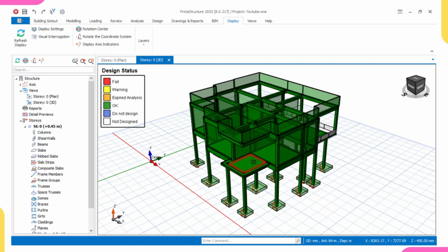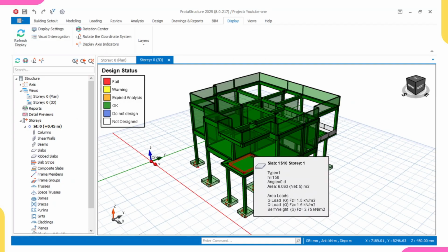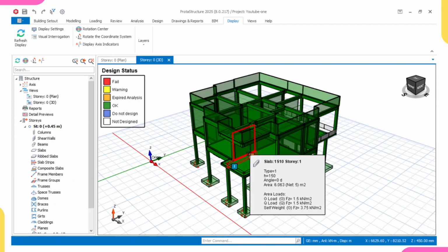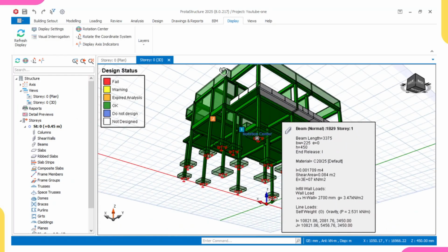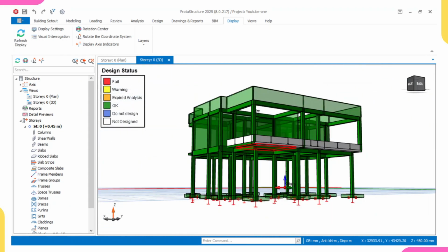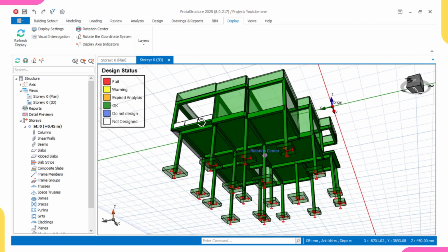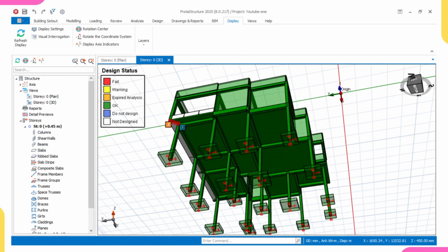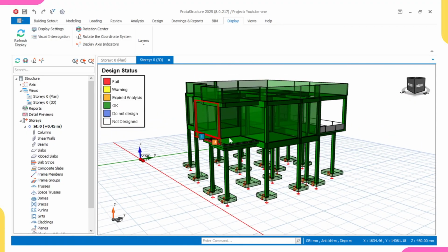You get to learn how we did our column placement, our beam placement, our paneling, which is slab, the governing principle that columns should not be more than 6 meters and slab area should not be more than 30 meter square. You also learn how we achieved this, like this column and this column are not in the same place, and how we placed this hidden beam, which is something like a slab stiffener. The link to all those videos is in this video description.